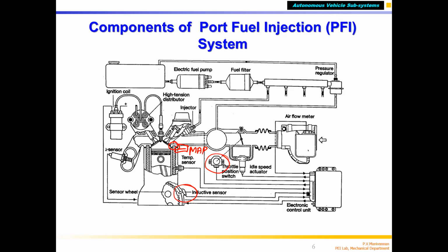That is load. How will you measure it? You put the MAP sensor here. When more load happens, more air goes in. Why? Because when the piston goes down, with the inlet valve open and the outlet valve closed, a vacuum is created. Air comes through the atmosphere, air filter and throttle control, and enters here.